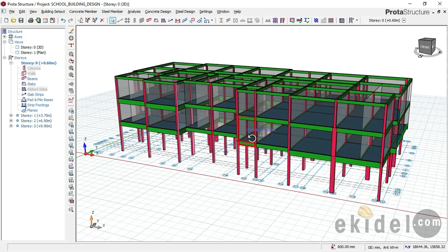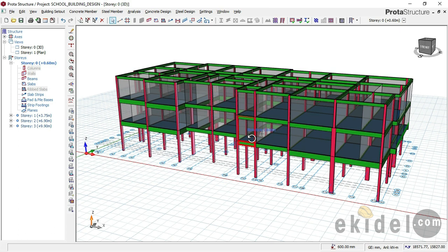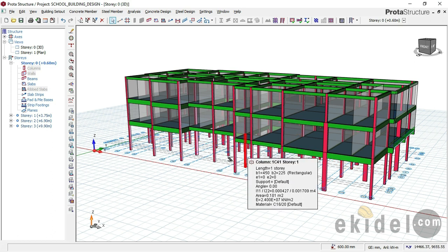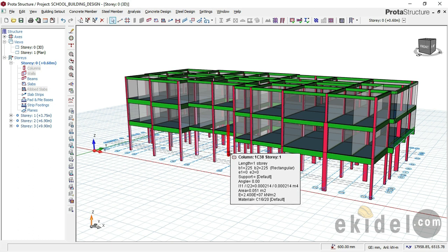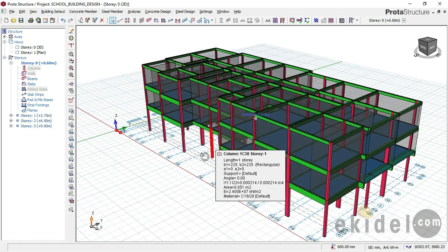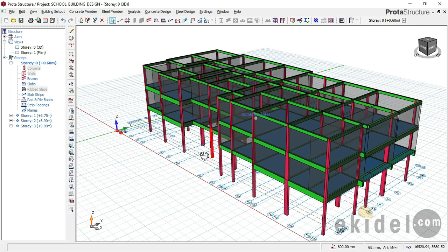The reason is because the bearing capacity of this building is 65 kilonewton per meter square. We tried using pad foundation and it was not working. It was failing. There was punching, and even when we increased the depth of the pad foundation, it was still failing. So we decided to use a raft foundation, and as you know, we have two types of raft foundation.